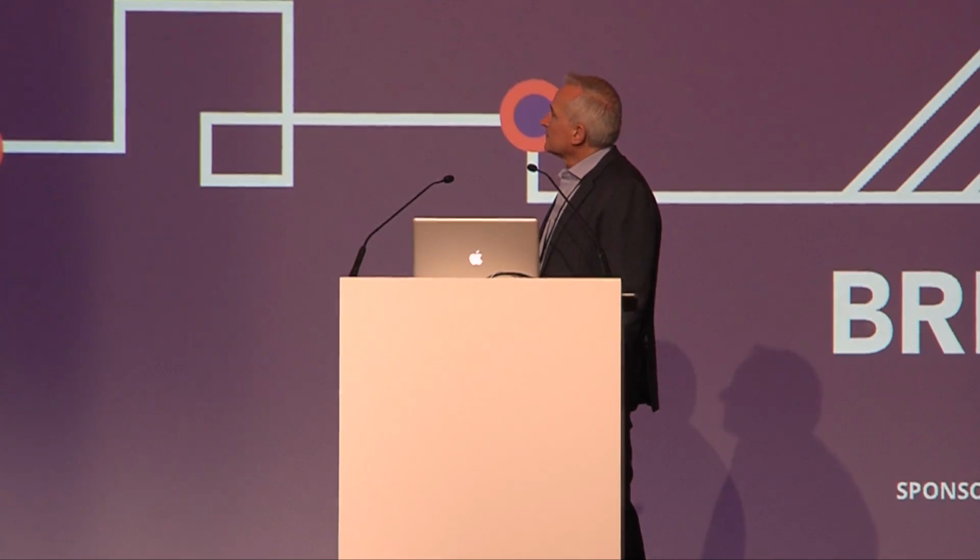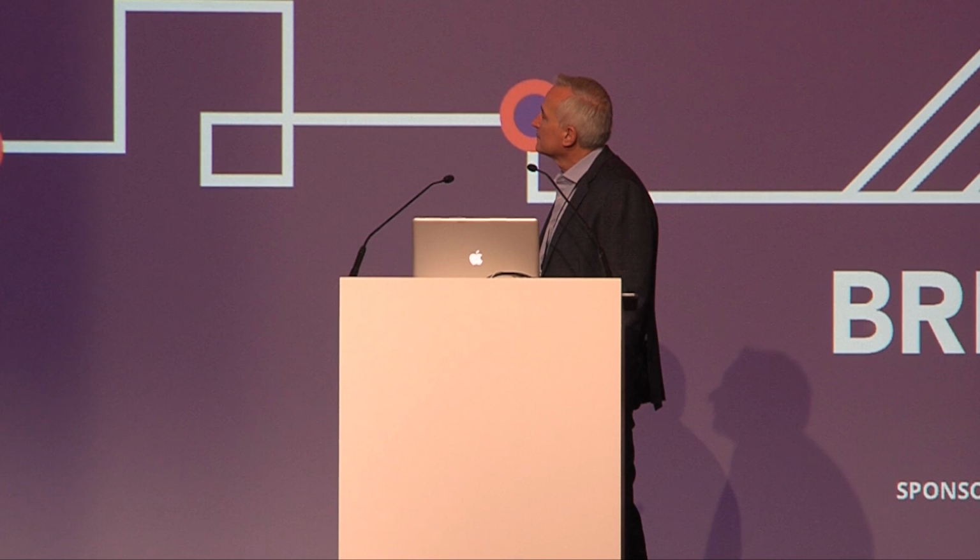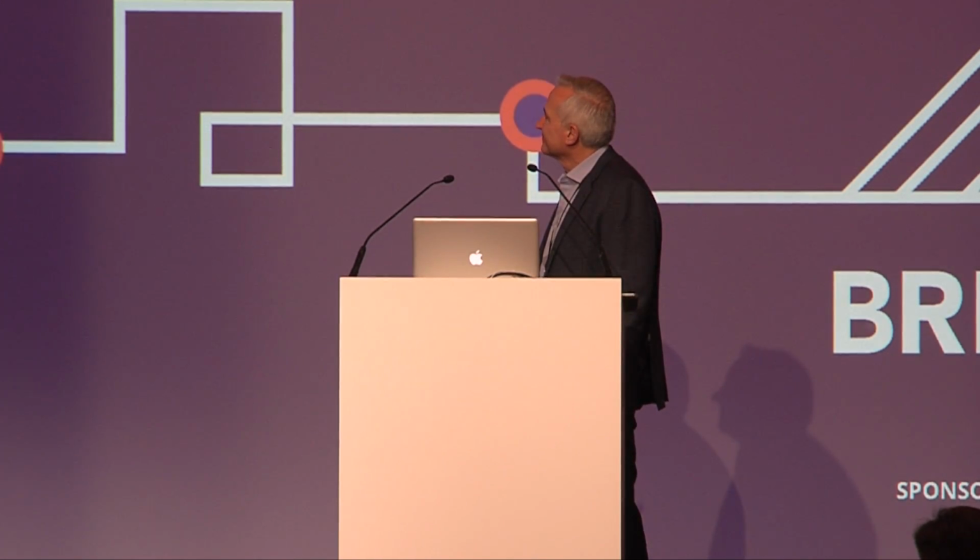You can have a quick look at dimension styles. Like if I select multiple dimension styles, like here, I immediately see the differences being marked in yellow. I can see only differences. I can have a quick preview of each dimension style. Now, many of these panels are quite interesting to have them around all the time, so we made them dockable, like the layer panel or the blocks. Let's see what you can do with the blocks.